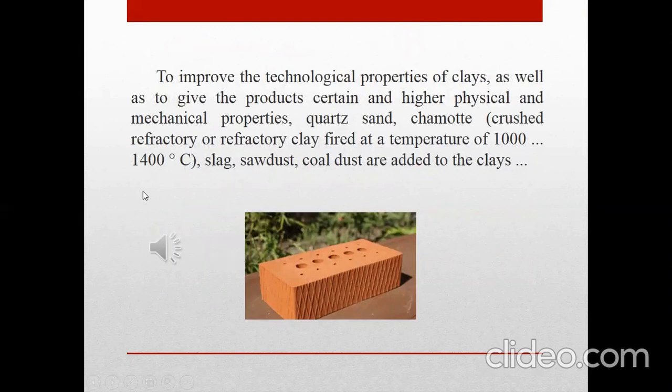To improve the technological properties of clays, as well as to give the products certain and higher physical and mechanical properties, quartz sand, chamotte, crushed refractory or refractory clay fired at a temperature of 1400 C, slag, sawdust, and coal dust are added to the clays.